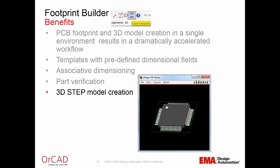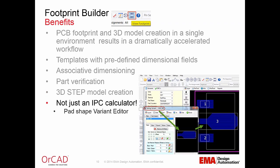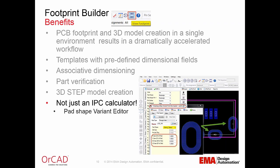The variant editor also allows you to customize for things like pin counts, pin configuration, and pad sizes that you might have to create. Again, that would be more from a recommended vendor land pattern. And then you can save those customized templates. Here's just another example of customizing pad stacks for a particular USB style connector, let's say.